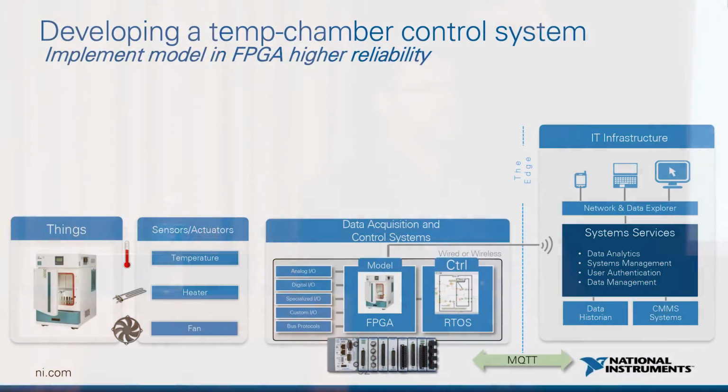Now, if you think about what can happen if somebody hacks in and changes your system, and it's something like a temperature, right? If you're trying to drive the temperature to be 40 degrees C or 50 degrees C, and they tell you it's at 20, you're going to turn the heater on. And you're going to run that heater indefinitely because you'll never hit your set point. That could happen. You also could be saying, it's 60 degrees, it's 20 degrees, it's 60 degrees, it's 20 degrees, and cycle that heater and break it, right?